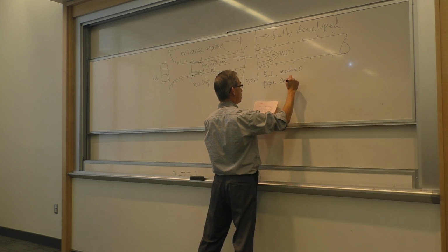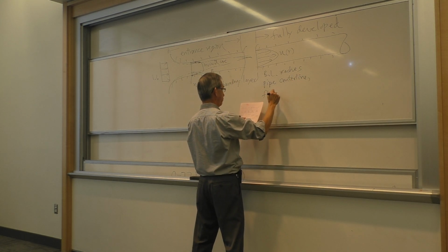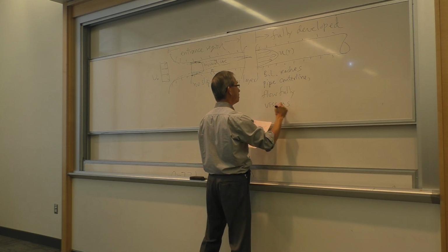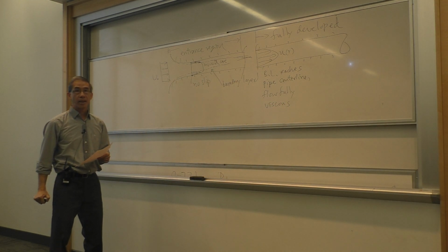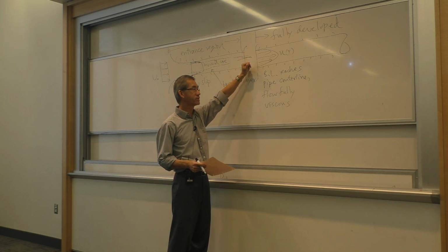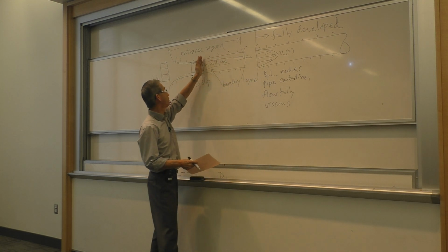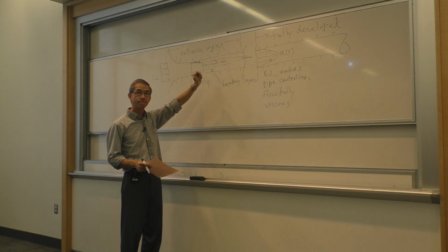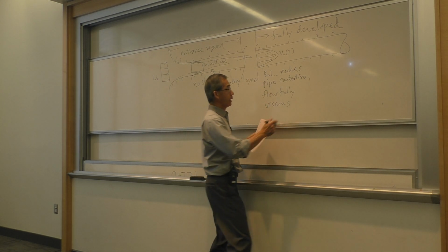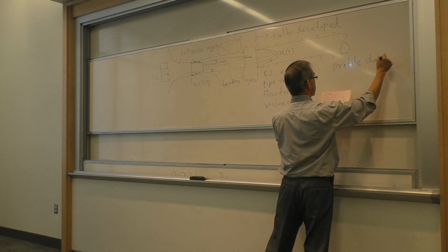Finally, from all the perimeter wall, the boundary layers finally meet. And the entire pipe internally is now influenced by viscosity. The implicit core disappears. There's no longer a flat top velocity profile. All right? Anything downstream of that is what we call fully developed flow. And the implication is that the profile will persist.